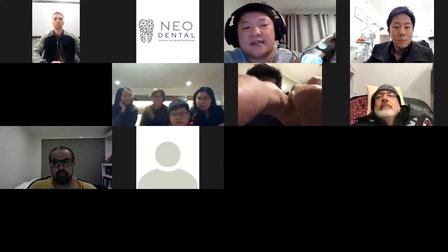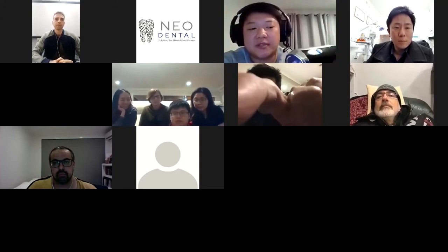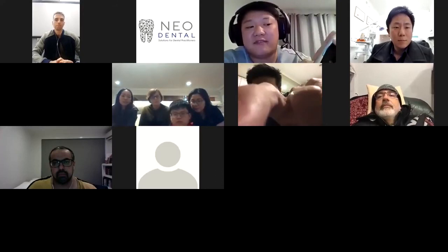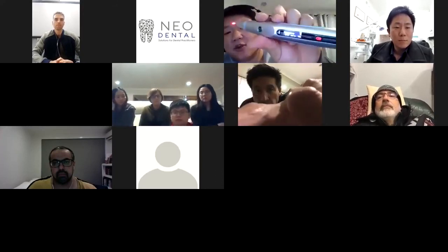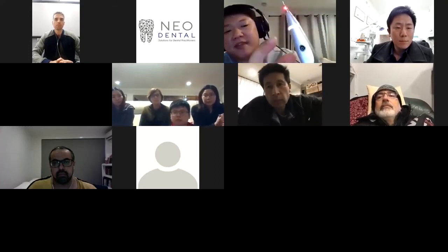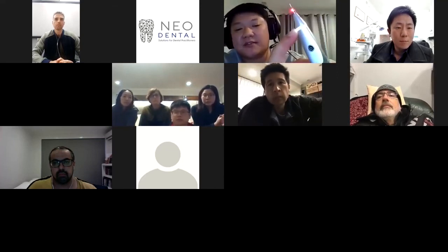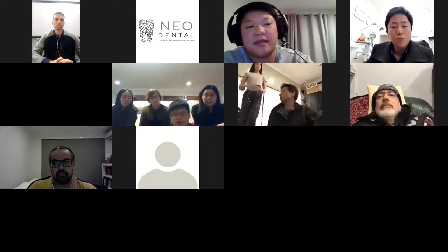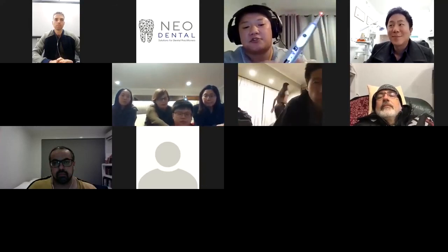Then you've got your standard and gentle mode. Standard is more of a continuous mode, and gentle is like a pulse. I find continuous just works well for me, and I haven't felt the need to change. So I click on standard. That's ready to go. But what you'll notice is you actually have to push down the circular button, and then the front part here lights up. That means that the laser is ready to go. When you're done with that, you just push the circular dot again, and then the light turns off.